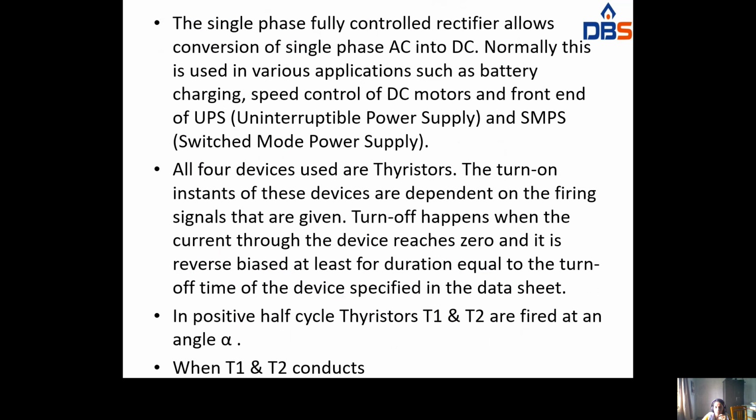Okay, next we have to see that the single phase full wave controlled rectifier allows conversion of single phase AC into DC. Normally this is used in various applications such as battery charging, speed control of DC motor, and front end of UPS, uninterruptible power supply, and SMPS, switched mode power supply.